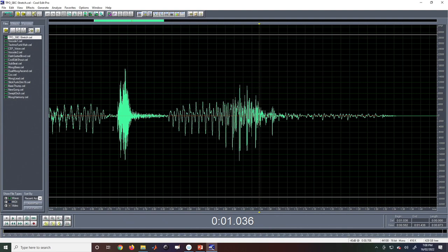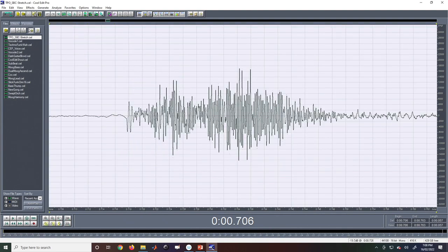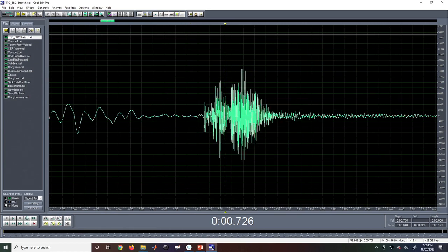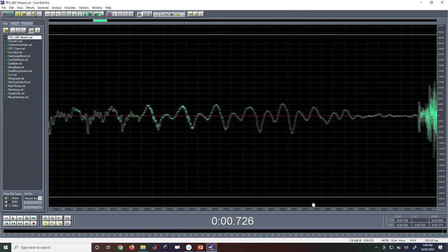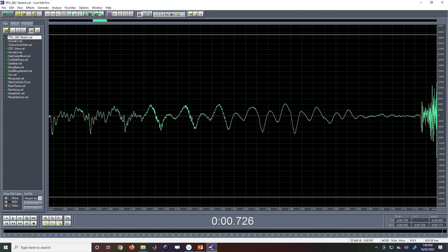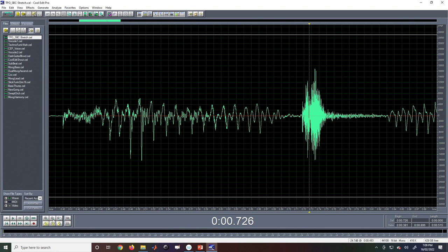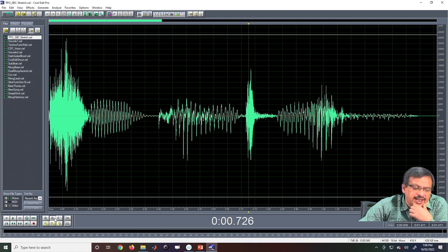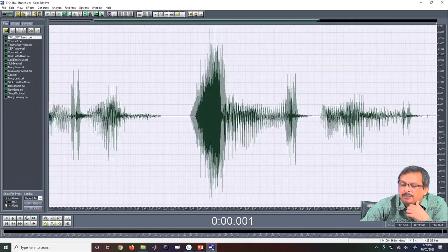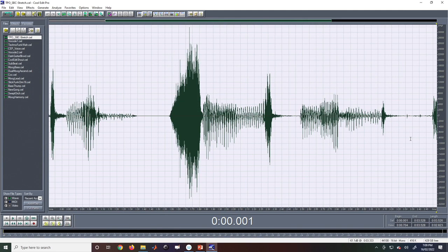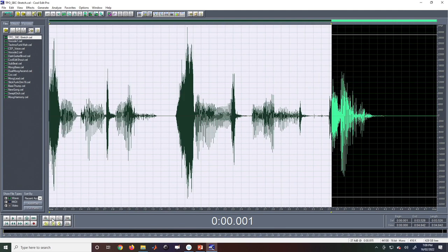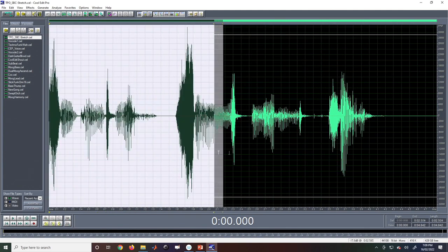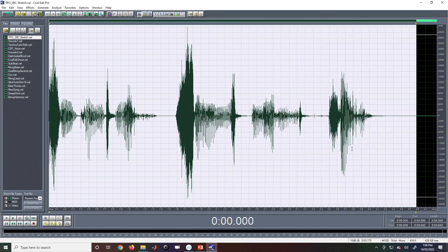This time it is noise, completely noise kind of thing. This time, if you see, it is periodic, and this time the periodicity also changes. So, the signal is not time independent, it is time dependent. In that case, if I take the entire signal and take the Fourier spectrum, what will I get? I get an average representation of the signal. That is not the correct analysis.